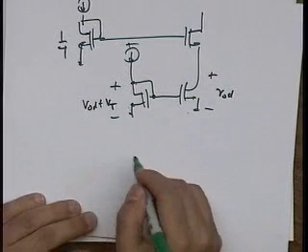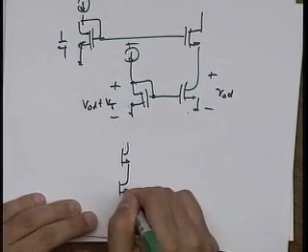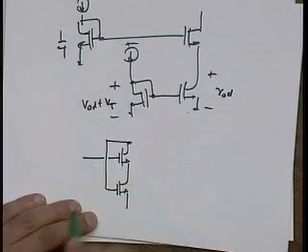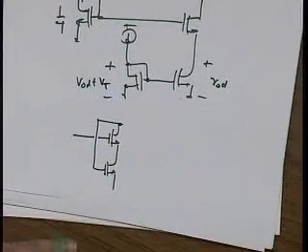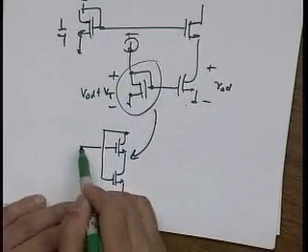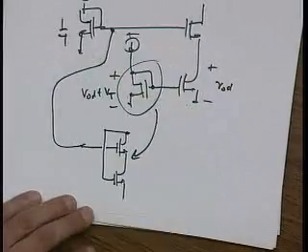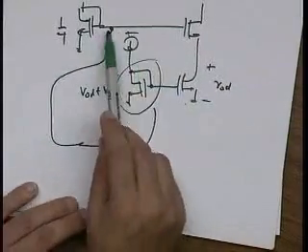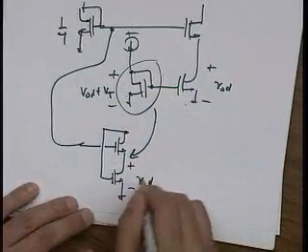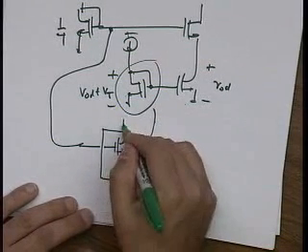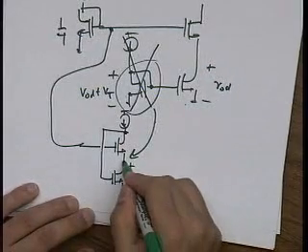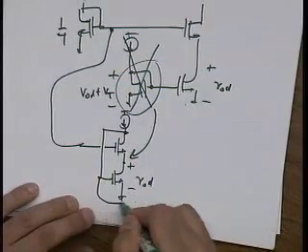All right? So the way to get rid of that systematic error is basically to use a circuit like this. Replace this transistor here with this transistor, where this voltage is also biased to this point, and so this voltage minus a VGS produces the same V overdrive voltage on this transistor, which is in my reference path. Okay, so now I'm going to get rid of this guy and connect this point, excuse me, to here.